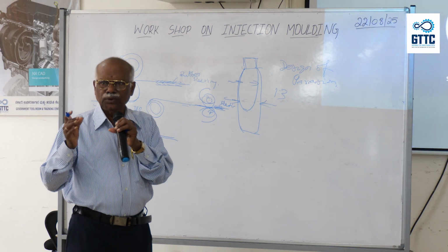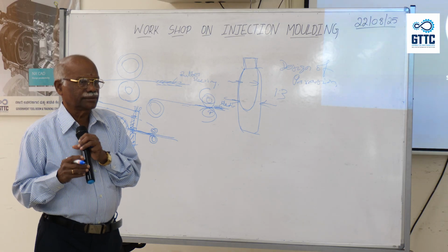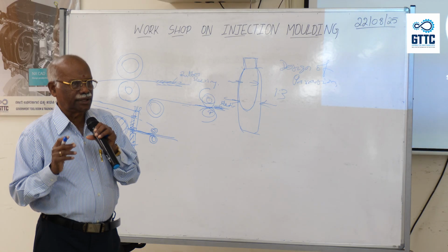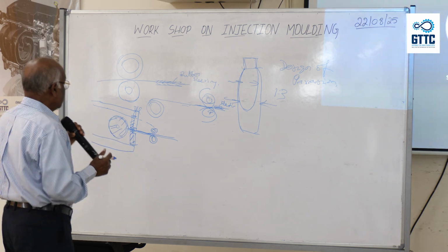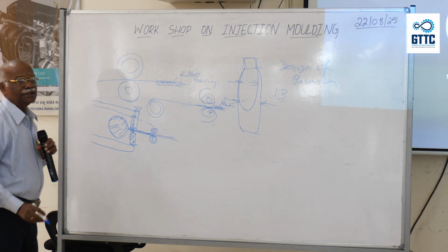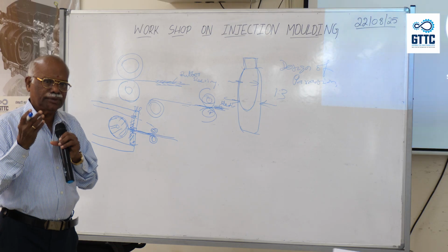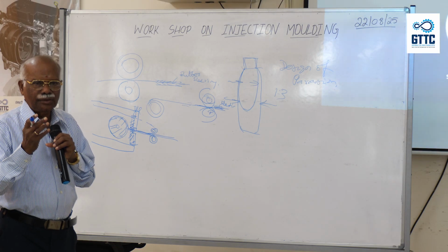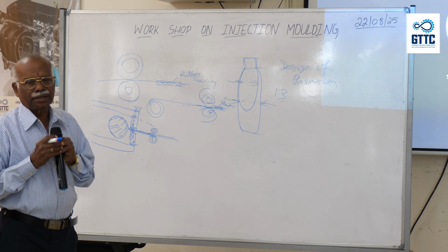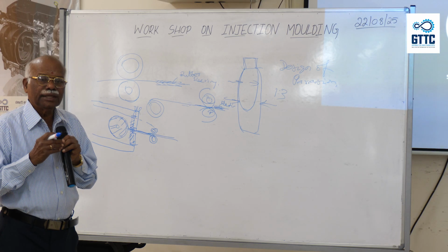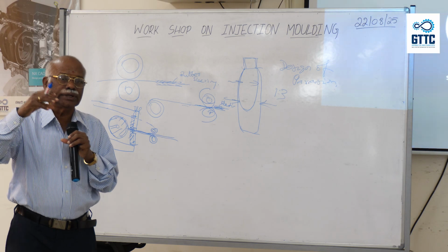When you happen to go on a visit to such an industry, you will have a clear picture. But here, as a designer, I just want you to be exposed to making the die for this extrusion. It is not a complicated die. When you specify a pipe, it is always measured and designed by its outer diameter. When you make a pipe, there will be a vacuum, created to maintain the outer diameter of the pipe.